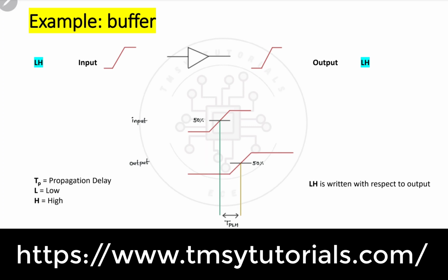Every gate and every combinational circuit will have some amount of delay associated with it. So this particular buffer will also have some amount of delay. You can call it tau D or tau PD, anything is the same. Tau is nothing but propagation delay. Here it should always be written with respect to the output. Here I have taken LH, which is with respect to the output. Why? Because the output is low and then it is going high, that is, from low to high. So that's why I am writing TPLH. This is when the input is going from low to high.